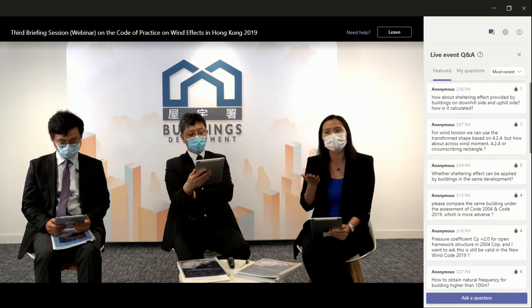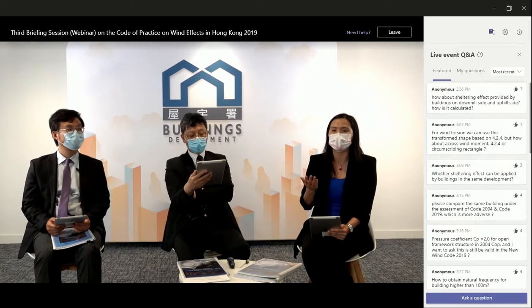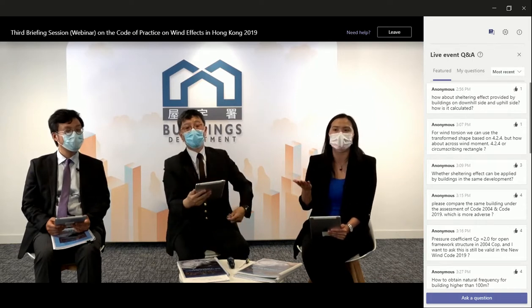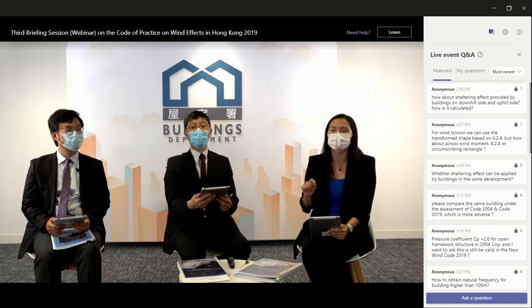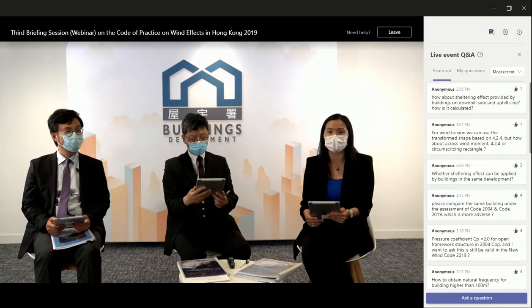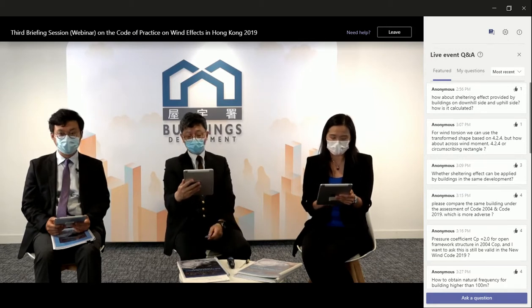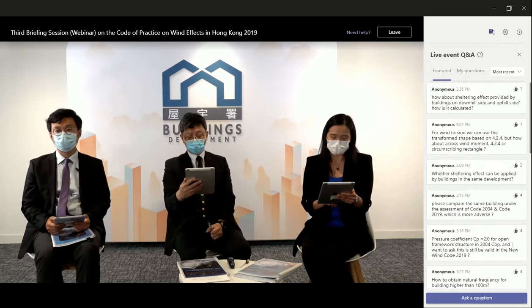And then the wind profile, how to spread it up to the story loads, should follow the wind tunnel test results, which means you obtain the scaling factor by using the total base moment and then apply this scaling factor up to the story loads. So we don't want to change the wind tunnel test. Okay, I hope this answers your questions.